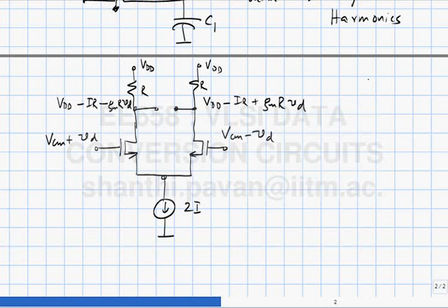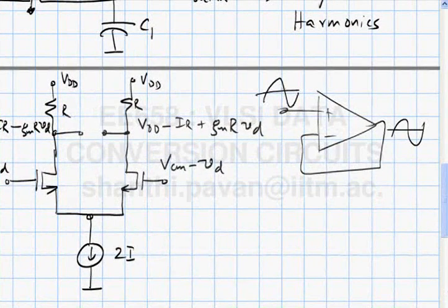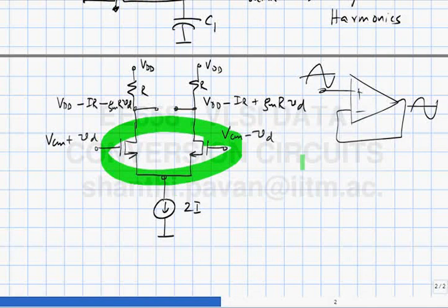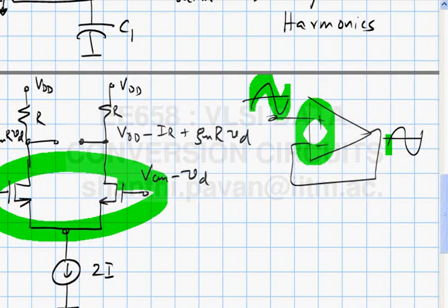For example, if I had an op amp hooked up like this, and the input differential pair didn't have any common mode rejection, then what do you think will happen? This is supposed to be a unity gain follower. If this does this, this is supposed to do the same thing. So what can you say about the common mode of the input circuit, given the difference between the two voltages? This contraption, without the tail current source, is sitting inside here. If this is a good op amp, then whatever this is, this also must be the same. Can you make any comment about the common mode that the input differential pair is seeing?